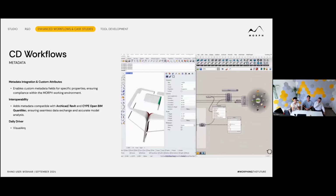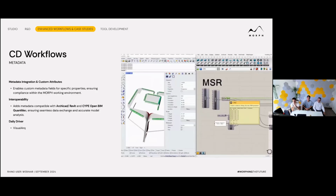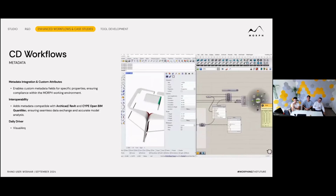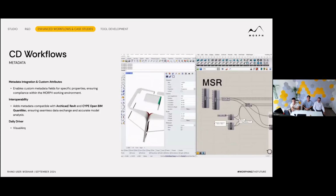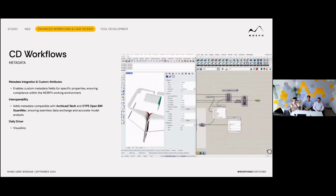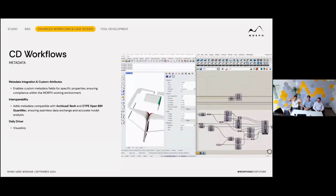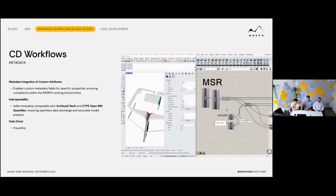For this metadata injection, we commonly use VisualARQ. VisualARQ is a plugin for Rhino and Grasshopper developed by Asuni CAD, which introduces BIM methodology to Rhino and Grasshopper. Apart from VisualARQ, there are many other plugins that we've already tried that allow working with metadata in Grasshopper and Rhino, like MetaHopper and Lunchbox. But we tend to use VisualARQ because we can generate IFC files with it to export to the rest of the teams.